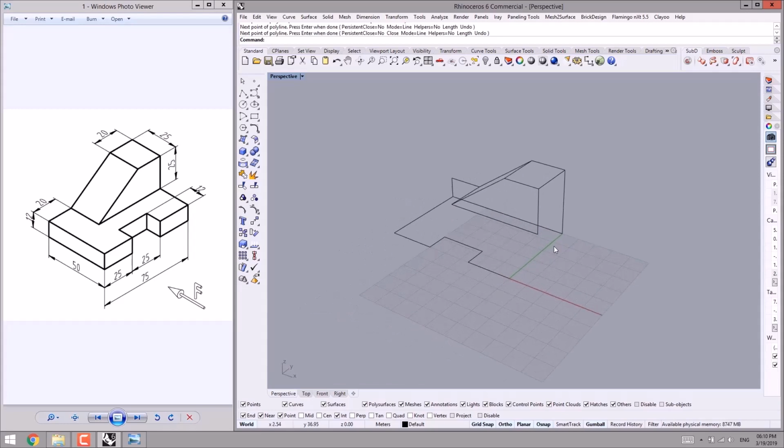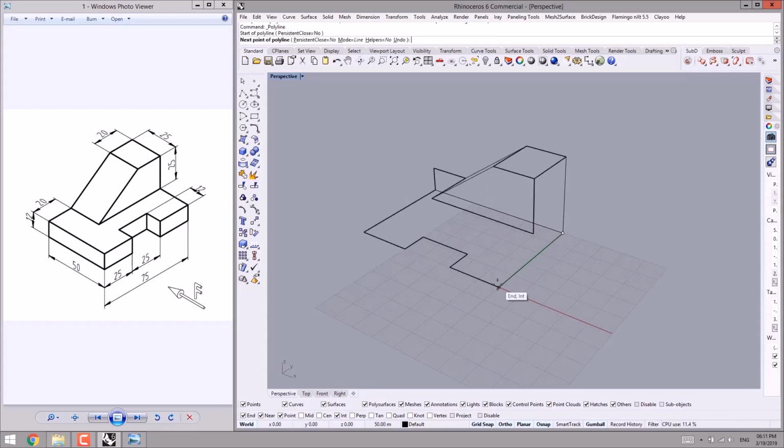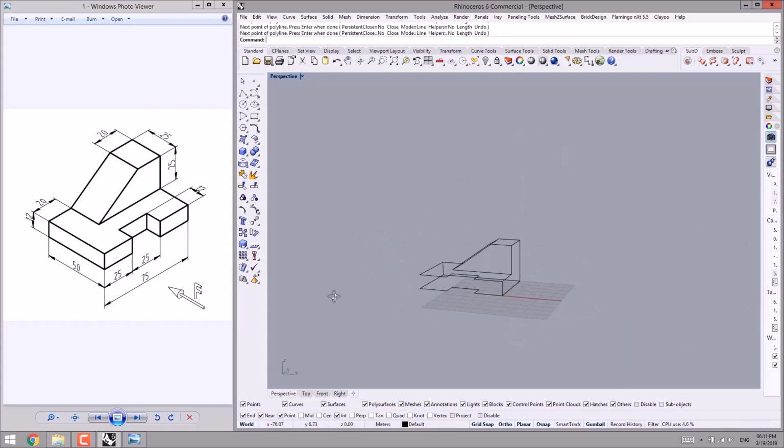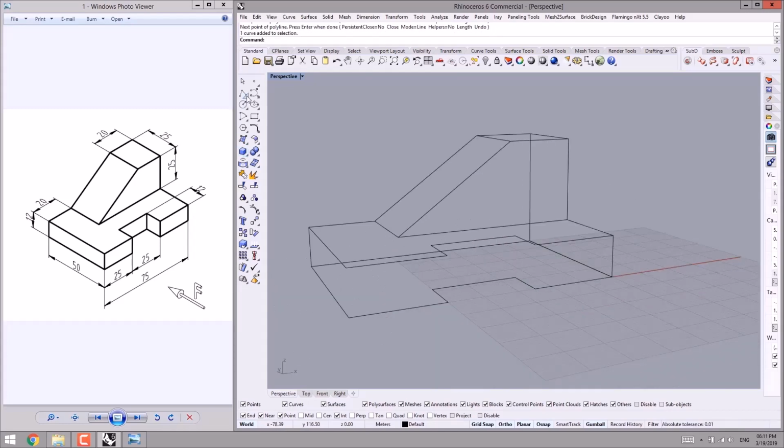Then by using right click, I start the polyline command. I start sketching, then I hold down Ctrl for sketching a vertical line at the size of 12 units or meters. Then I connect it to the intersection. Well done. Let's start again. 25 meters, I enter and click, 12, just like the image. 25, 12, 25, and then at last I connect it to the point this way.